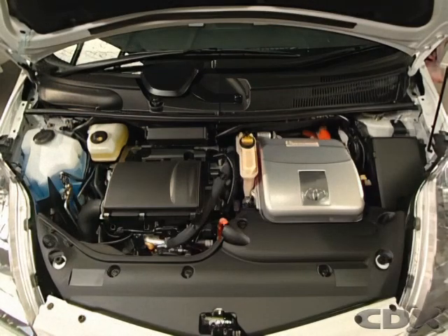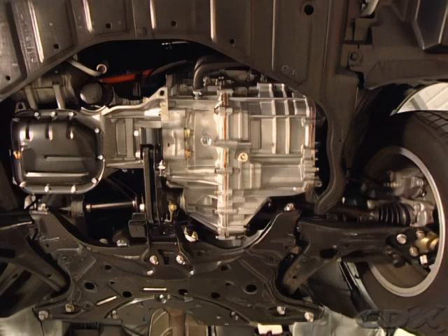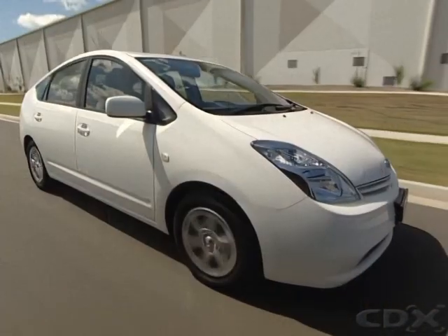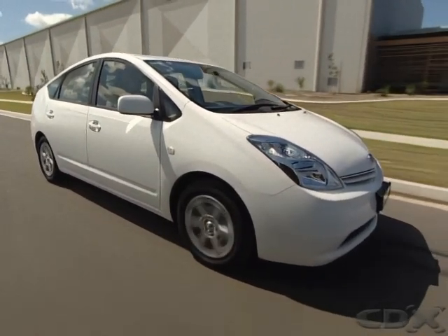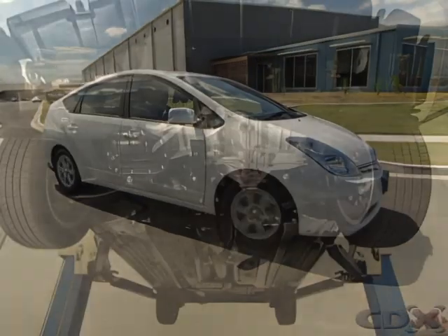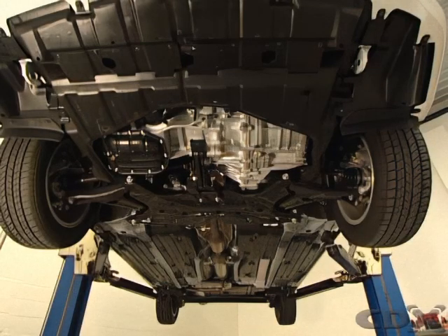The lower maximum operating speed allows engine components to be of lighter construction and weight when compared to a conventional engine. Lighter and smaller components reduce friction and increase engine efficiency. In addition, the crankshaft is mounted slightly left of centre. This has the effect of lessening major thrust load on the piston, reducing friction.